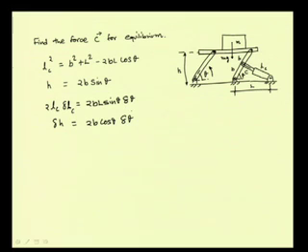Now, the work done by the weight and the work done by this force can be computed. When the link is displaced by a virtual displacement delta theta, this mass is raised or lowered by this amount, that is delta h, and the length of this link changes by this quantity delta L_c.